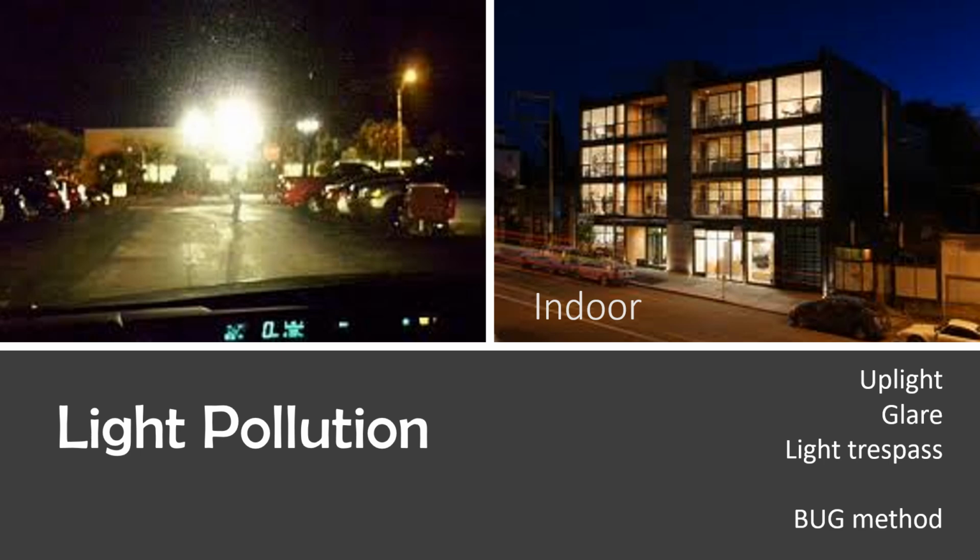Strategies to minimize light pollution include, for indoor, you can use indirect interior lighting, you can shut off non-emergency lighting, and you can shield lights to keep them focused on their target area. For exterior lighting, you can design with a computer model and only light for comfort and safety, reducing non-essential lighting, especially on the facade, and prevent uplighting.